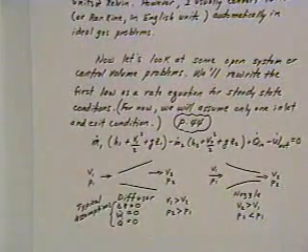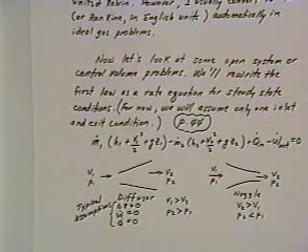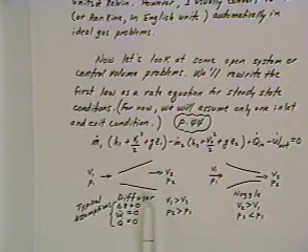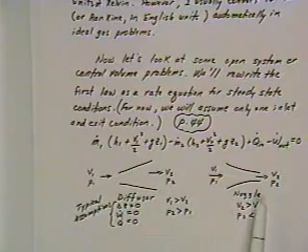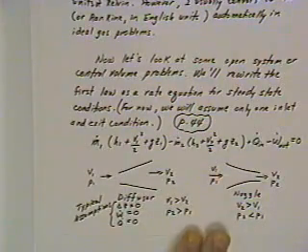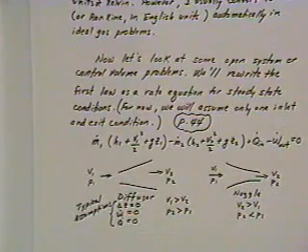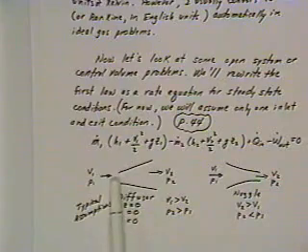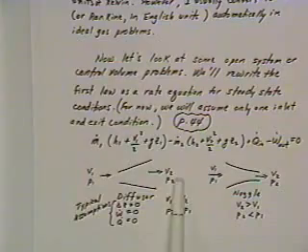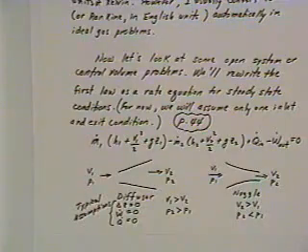Okay, now there are a couple of different problems here that we'll work out involving first law examples for open systems. We'll start out first of all with a diffuser, and then secondly a nozzle, and let's go over the assumptions that you're typically going to be making in these. If you have a horizontal device, such as a nozzle or a diffuser as we've drawn it here, the entering potential energy and the leaving potential energy are going to be the same. They're at the same elevation, so the change in potential energy is equal to 0.